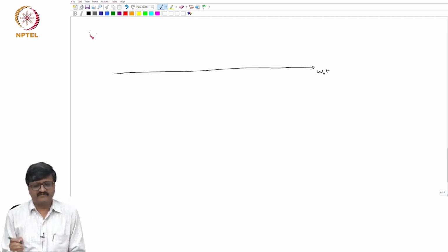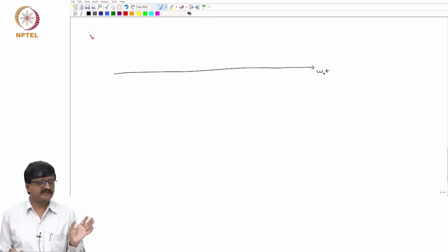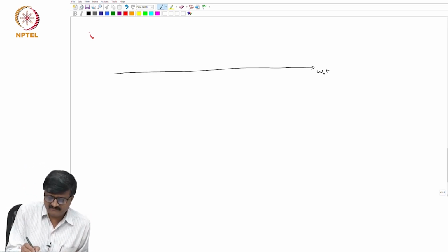The waveform for say IB, which is one of the AC side currents. So, it has only 3 possible values. IB has 3 possible values, ID or minus ID or 0. So, it is equal to ID for 120 degrees, it is equal to minus ID for 120 degrees, and it is equal to 0 for another 120 degrees. So, the waveform is like this.